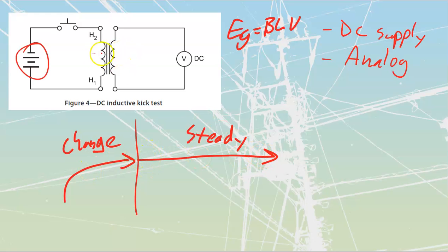Once we get to steady state current, this thing is going to have lines of flux stretched around it, but they're not moving, they're not contracting, they're not expanding. Therefore, what we have on this side is no longer affected. We don't generate anything on this side. On a transformer, when we feed DC into it, we only generate for 5 tau. Right? That's this over here.